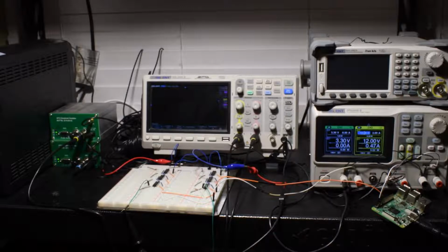So this is the complete setup that's actually running right now, and the way it works that's different from the last setup we looked at is that the two GPS disciplined oscillators are connected to the DC power supply, and that's at channel 2. And the good thing about that is that we can apply power to both of them at the same time, and it also makes it easier to make sure that they have a common ground with the rest of the system. The ends of the two chains are still connected to the two channels of the oscilloscope like we saw before.